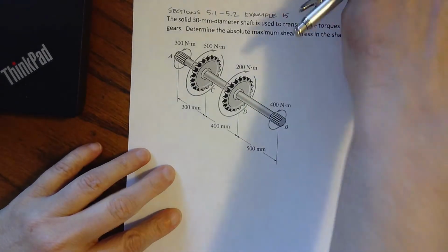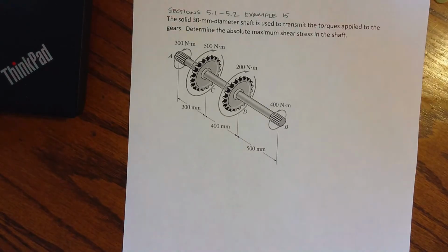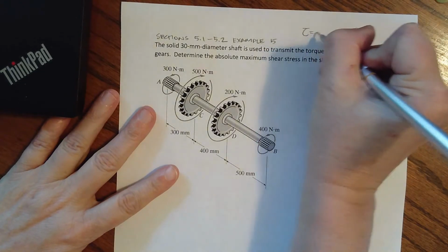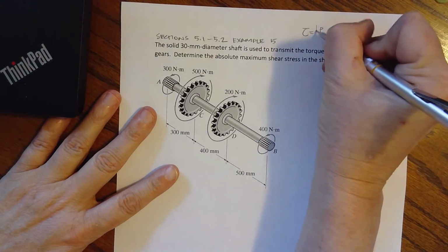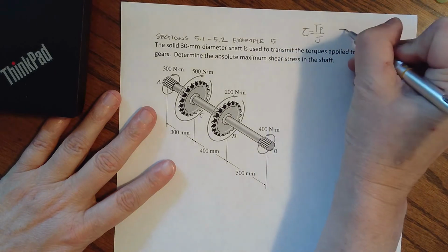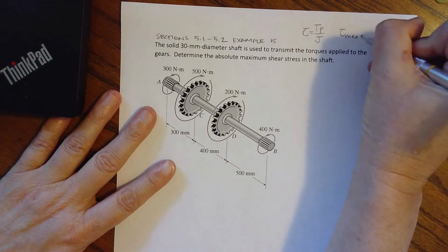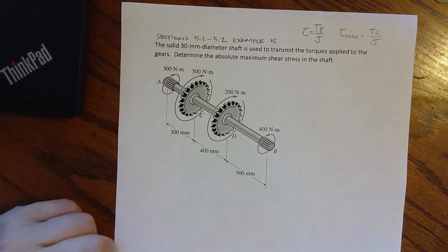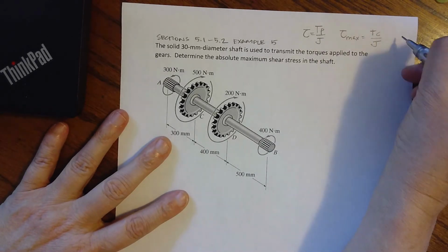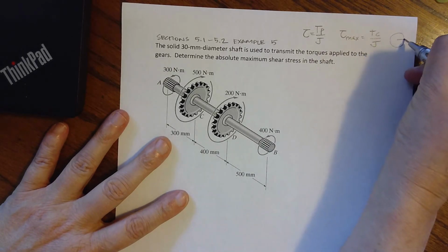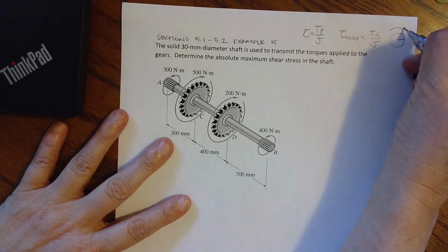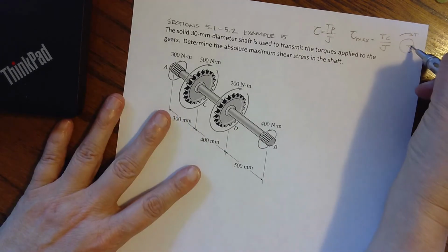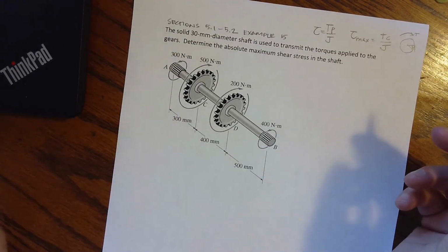Okay, so here's our final example for sections 5.1, 5.2. We're just looking at shear stress due to torsion. And remember, we have shear stress equals T times rho over J, and that's along the radial length. If we want the maximum, it's going to be the torque in that cross section times C, which is the radius, divided by J. C is the radius, and remember it varies linearly as we move away from the center. If we have a torque applied in that direction, then we have this nice linear distribution of both our strain and our shear stress.